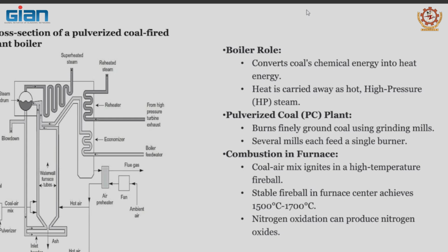If you look at proximate analysis of a coal, you will notice that there is some nitrogen, but that's not the nitrogen that gives us nitrogen oxides. At this higher temperature, you may check in your textbooks, or with your professor, something called the Zeldovich reaction, which is the fixation of atmospheric nitrogen that is released, and that nitrogen reacts with oxygen to give us a lot of nitrogen oxides.